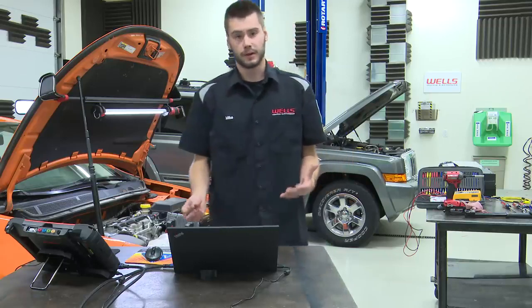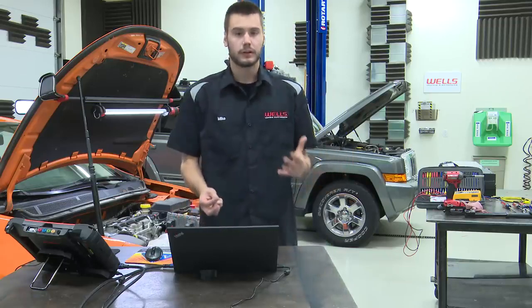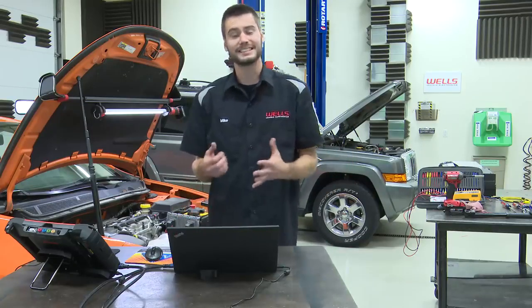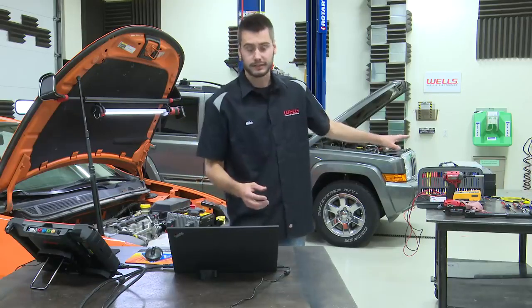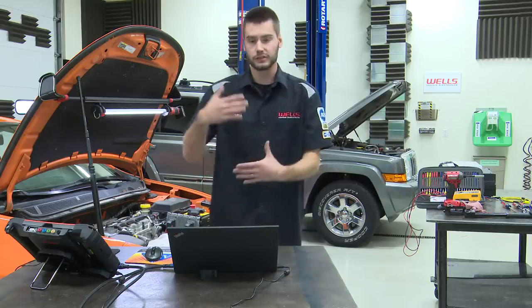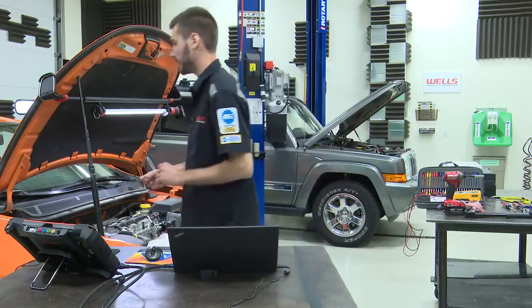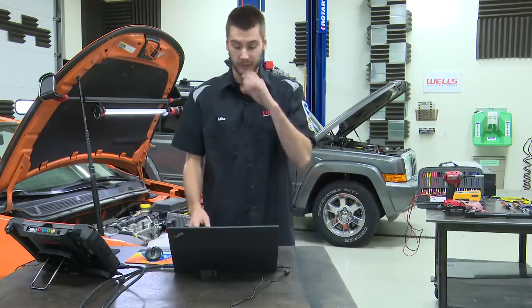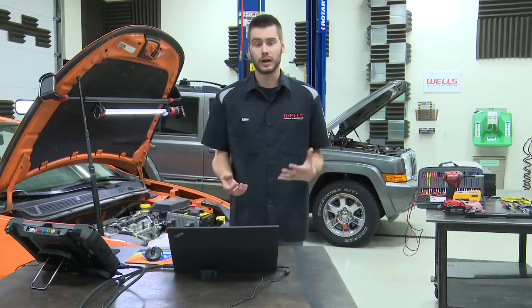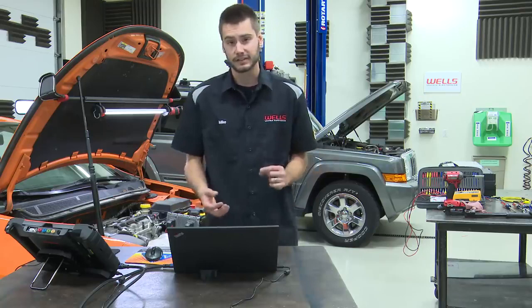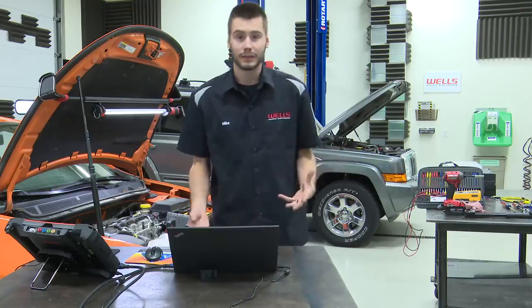Let's scope it, right? Let's get our lab scope out and throw a scope on it and see exactly what it's doing. Our ohm meter, sure, it reads continuity across our circuit. Yeah, sorry, Jim, you can go ahead and put it back in park. It reads continuity across our circuit, wonderful. But that ohm meter is slow. Our computer reads that circuit a lot faster than that ohm meter is going to read it. We need to use a lab scope.